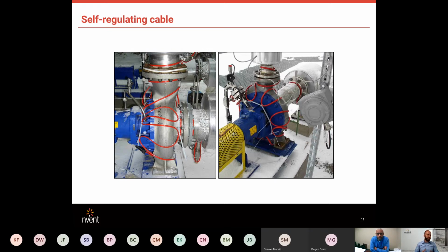You have to do an additional wrap for all your valves, flanges, and supports, along with an extra loop for all your components for a service loop. A service loop means if that component breaks or gets damaged or needs to be pulled away from the pipe, you have some slack in that cable. So it's not really uncommon to have 1,000 feet of pipe and need 1,600 feet of heat trace cable. That's really a typical ratio of cable to pipe.